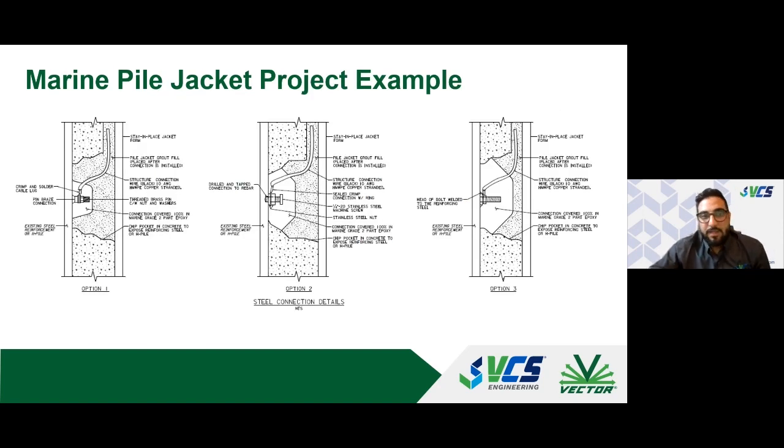And so as part of that, having structure connections and ensuring electrical continuity of all the steel elements inside your structure element is vital. The first step is to make sure that all of your steel components that you would like to protect are electrically continuous with one another. Once electrical continuity is established, then the next step would be to install structure connections.